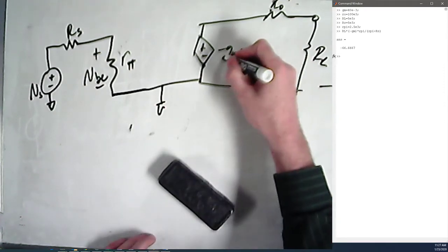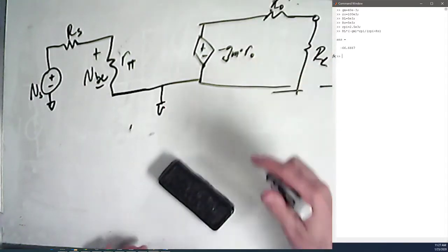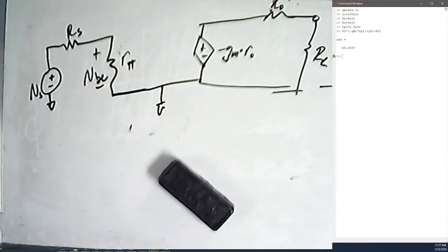In other words, this is a lot easier to deal with. We understand the voltage divider over here. Life is really well, and so let's just calculate that really quickly. What we end up with is negative gm times ro is equal to minus 4,000. Of course, they were saying that that was infinite, or that was an infinite resistor. It was so big that RL didn't even touch it. So we're not going to go into that too much, but that's the way we translate this into a voltage gain circuit rather than a current gain circuit. So I think that's a really good example of why we'd want to transfer a current source into a voltage source.